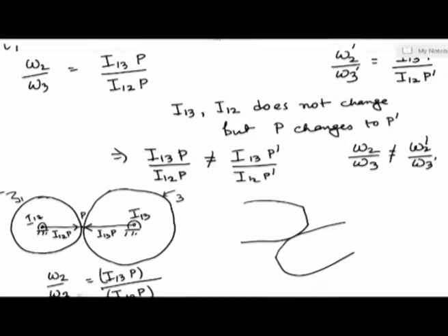So, now this ratio we can identify to be the ratio of the radii of the two friction disks, and therefore this point P comes out to be the pitch point of the friction disk. So, that is the equivalent motion. So here, just to repeat the arguments, these were the 2 points.